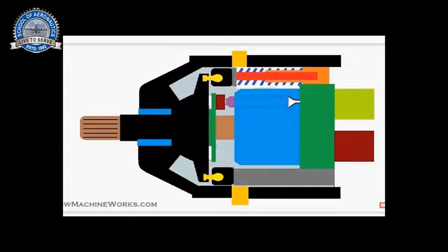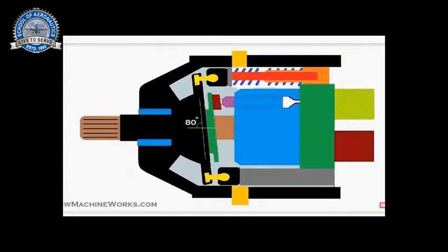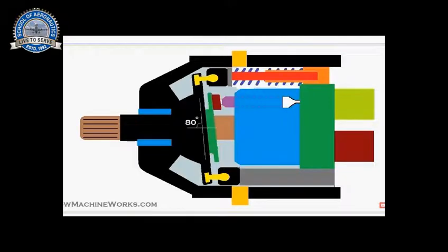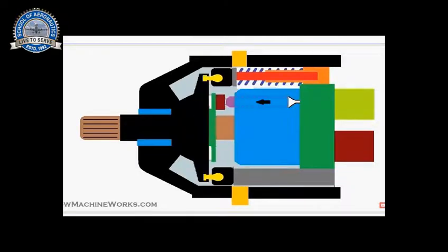So I'm pressurizing the valve so that the swash plate angle can be changed. You can see it's in 90 degree. When the pressure hits, the swash plate angle changes to 80 degree. You can see a decrease of 10 degree over there. So at the top, the swash plate moves back, and at the bottom, the swash plate moves towards the front. And have a look at the piston. See the arrow mark. The piston is actually moving back, and that's the reciprocating motion happening.